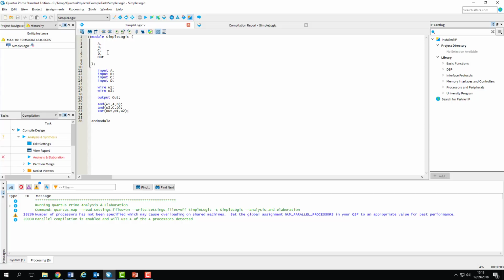So what I've done here is add two more inputs, C and D. I've also added a couple of wires to our design so we can connect between the gates. Wires in Verilog work similar to how they do in Jack, so just add them in like this for now. We'll come back to the syntax in the next lab session. I've made the circuit a bit more complex with some extra gates, so we'll compile this and see what we end up with.